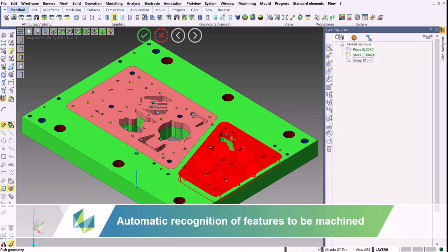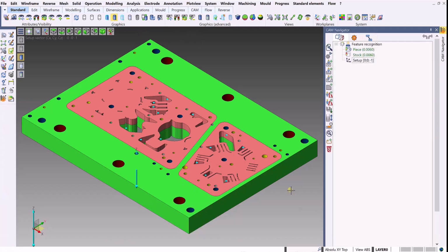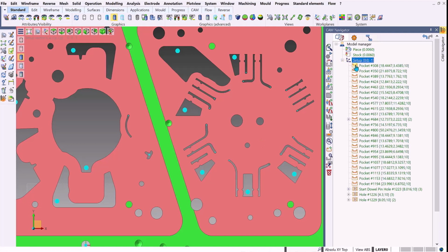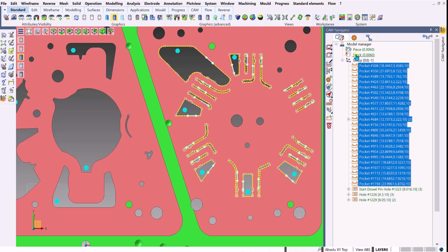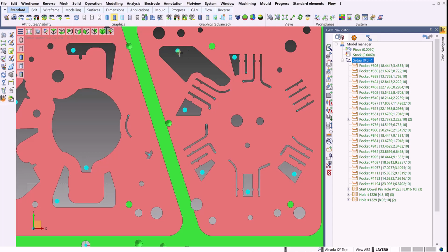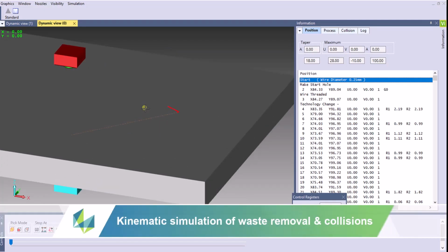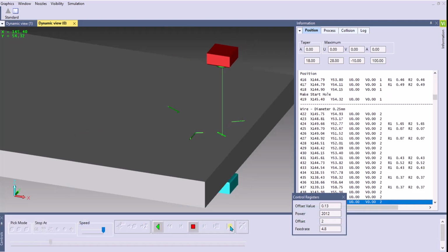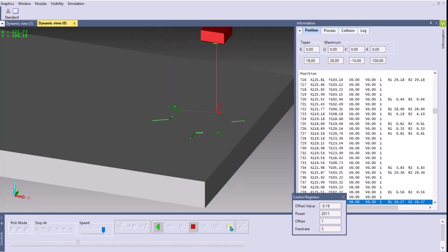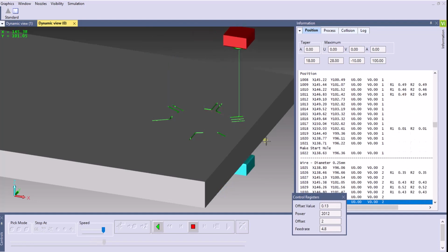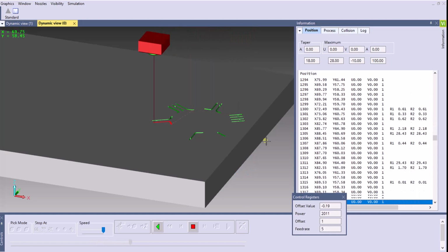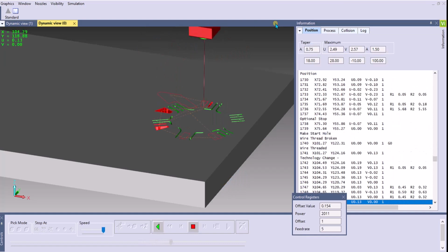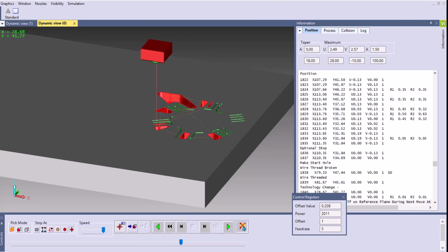The EDM process allows for high accuracy, particularly for complex, precise shapes that are hard to machine. Wire EDM can be used for any conductive material, including hardened workpieces and metals that are challenging for traditional machining techniques. Complex punch apertures and the corresponding solid punches are efficiently manufactured with seamless integration to wire EDM. Keeping the model within the same product environment throughout the design cycle, from design to manufacture, will guarantee data consistency and significantly smooth the design process.